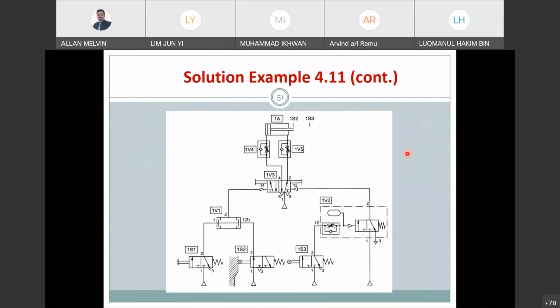So you can look here. You have a push button and this is always on. That is why it has a picture like a wall here. The meaning is it is on. If there is no wall like this, it means it is off. That is why here is on the left hand side, here on the right hand side. So if you draw a contact, make sure you draw it on the left side. Don't make the connection on the right side. This is already wrong. So end valve, push button and roller on, you send a signal, the cylinder will extend.